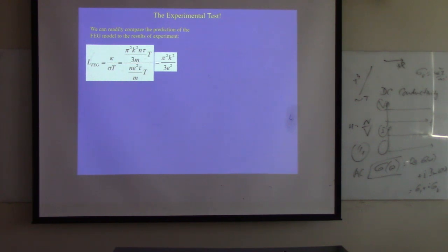So you can decrease the phononic thermal conductivity, and then you can make ZT large. So how do you decrease the phononic thermal conductivity? You have to introduce more phonon scatterers, right? So the phonons can scatter without affecting sigma. There's a lot of work going on in this area.